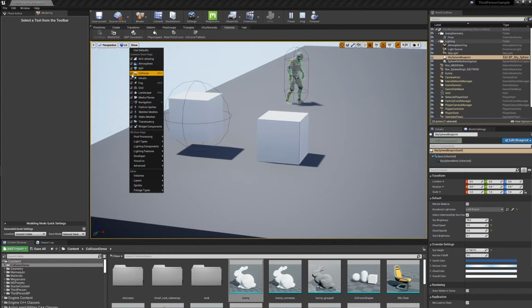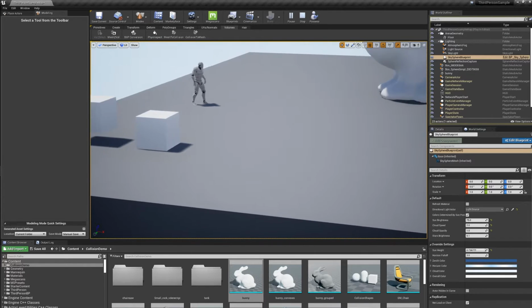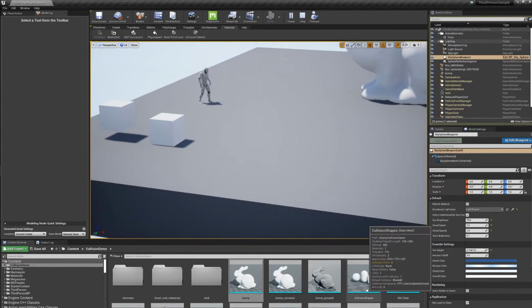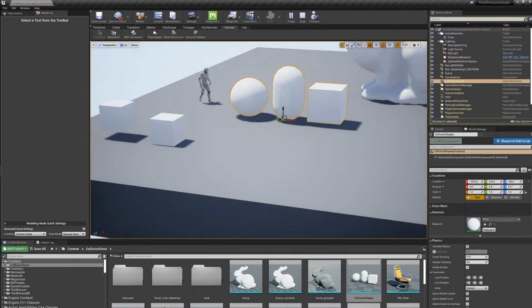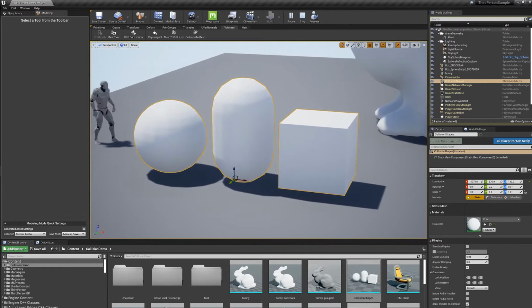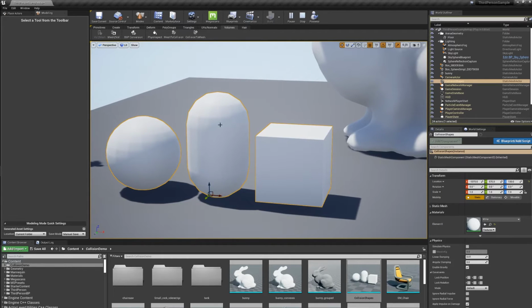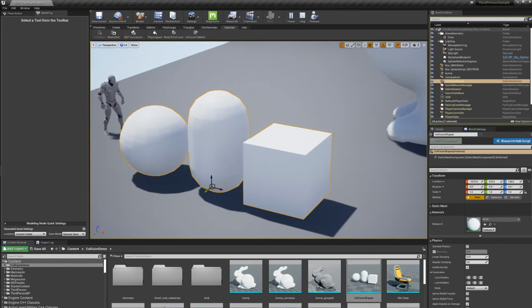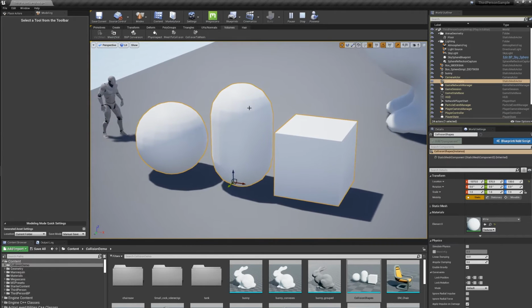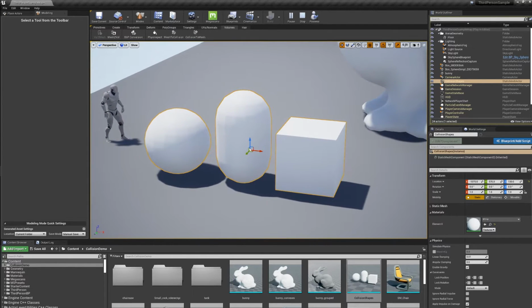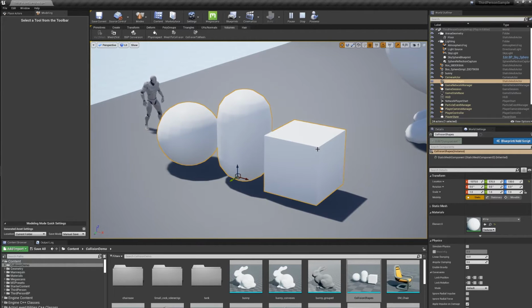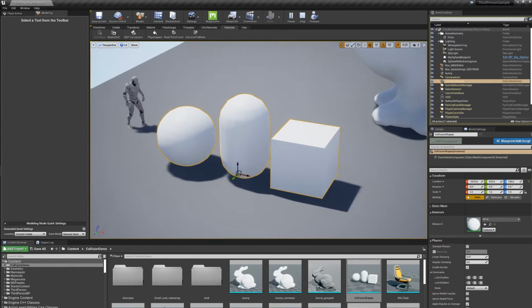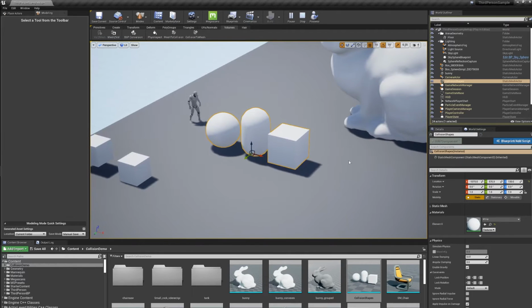And for more complex shapes, what we're going to try and do is approximate them with simple collision. Now, when I say simple collision, what do I mean? Well, there are certain simple collision shapes that are supported. There are three basic shapes, which are spheres, capsules, or sometimes they're called spheres, like sphere cylinders, and boxes. The sphere can be any radius, but it has to be a sphere. The capsule can be any length and radius, and the box can be any box dimensions, and it can be rotated. Any of them can be rotated. But those are the three shapes that we have, and I'll show that as we go along.